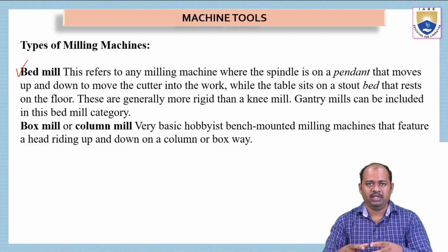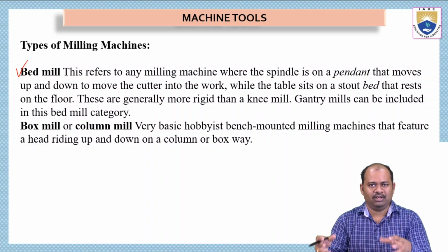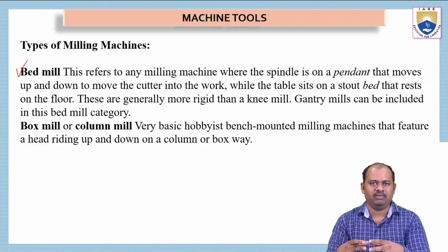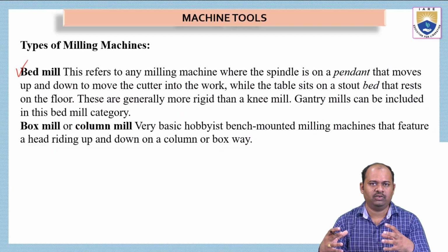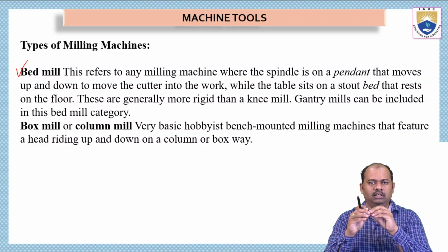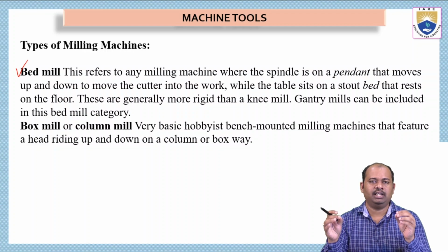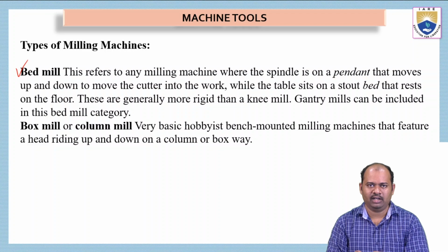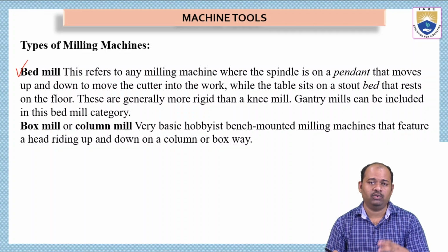Okay, the workpiece itself can be kept on the ground without any attachment or placement. That means we don't need any chuck here. We don't have to place the workpiece in a vise. The workpiece is so huge that it is simply kept on the ground, and the milling machine equipment is attached on the gantry. A gantry is nothing but a frame attached on a column which is very tall, about 100 meters, or 50 meters.